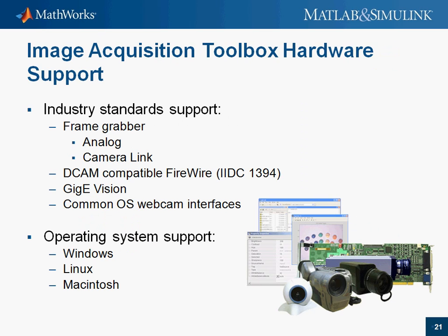We've taken a good look at what the products can do and how we can use them in some demos. For now, I'd like to take a moment to cover the breadth of what Image Acquisition Toolbox supports. Now, our conversation has been oriented around GigE Vision cameras for now, but the nice thing about the product is that it's set up so that you can change cameras depending on your needs. So the code we saw today could easily be modified to work with FireWire cameras or CameraLink cameras, for example. Now, I've listed some of the types of camera interfaces that the toolbox supports.